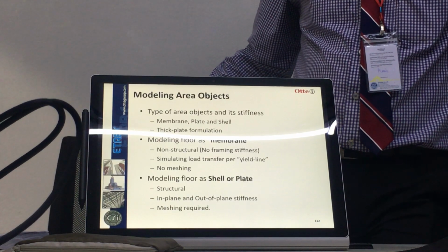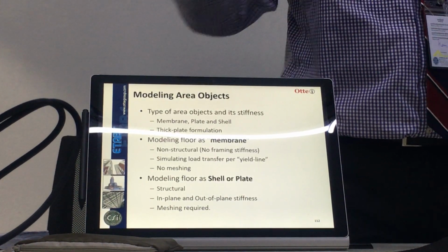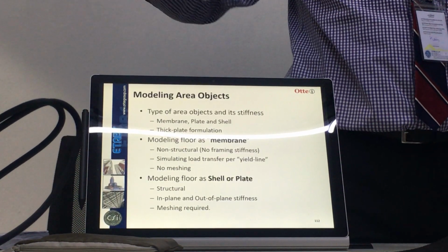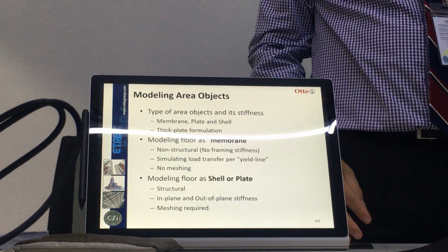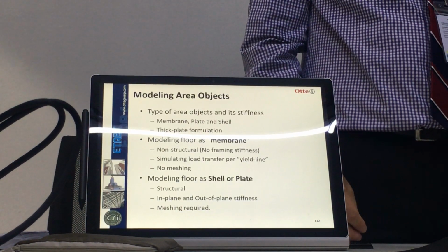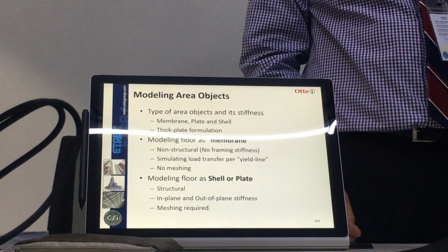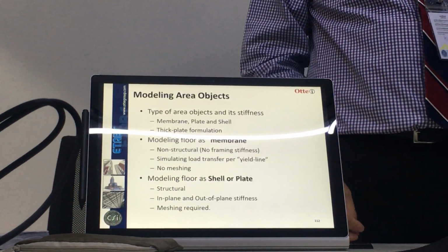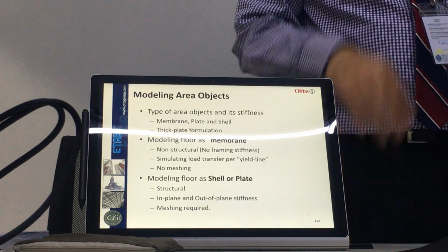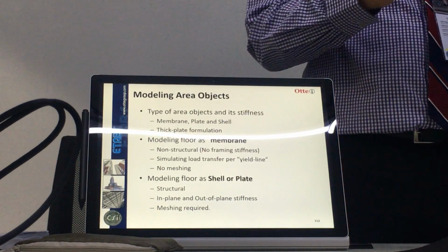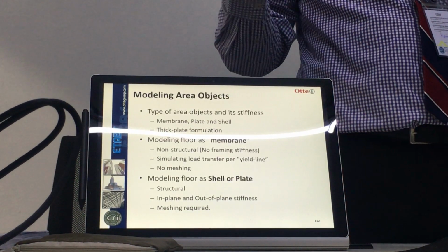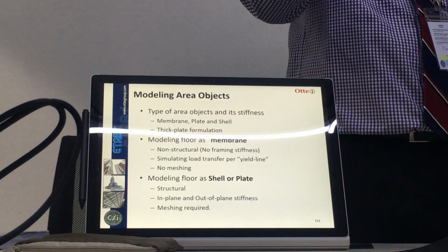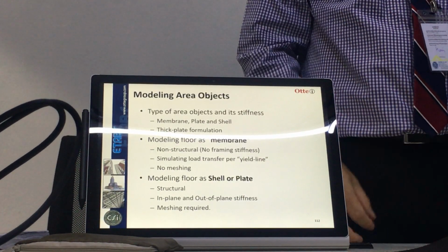Think about it. A fat beam, you also don't want to model as a solid, because it's simple to do a line, right? Now you change the fat beam to solid. In fact, when you do solid, it's very difficult to understand the stress. Anybody who does solid always uses the Von Mises stress. Von Mises stress is used in allowable stress design, non-directional. It just gives you the magnitude of the stress, and you make sure you don't exceed the limiting stress, that's all you do. So not necessarily is the higher order element like 3D better than 2D, or 2D better than 1D. It depends on the usage. Okay?